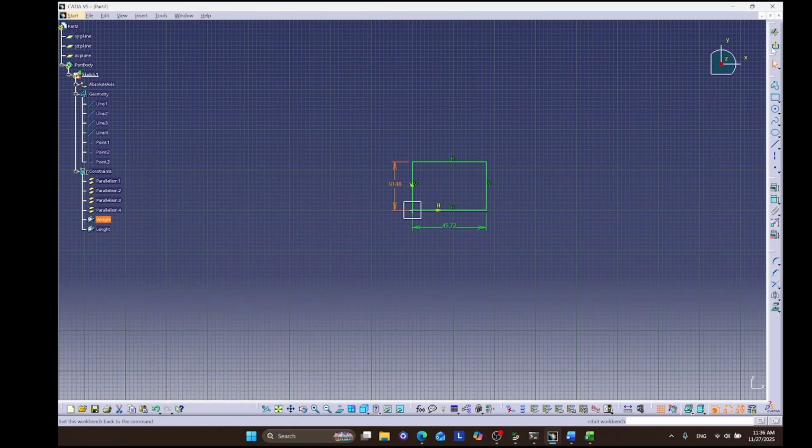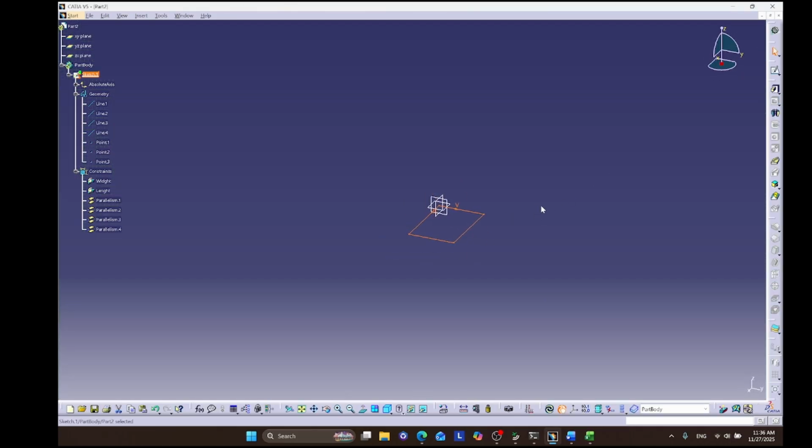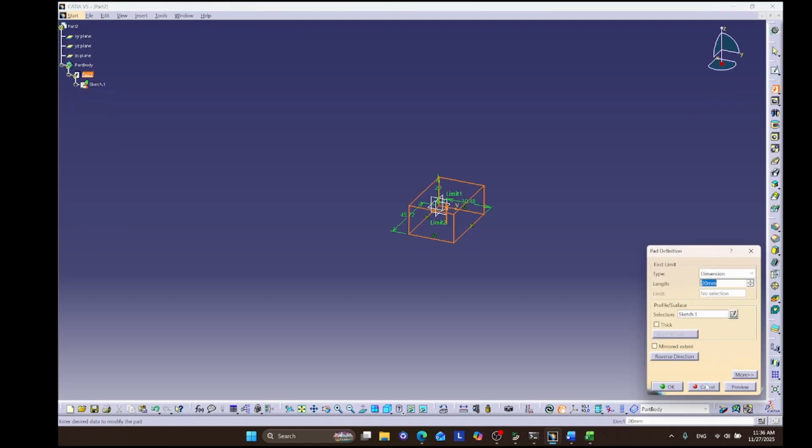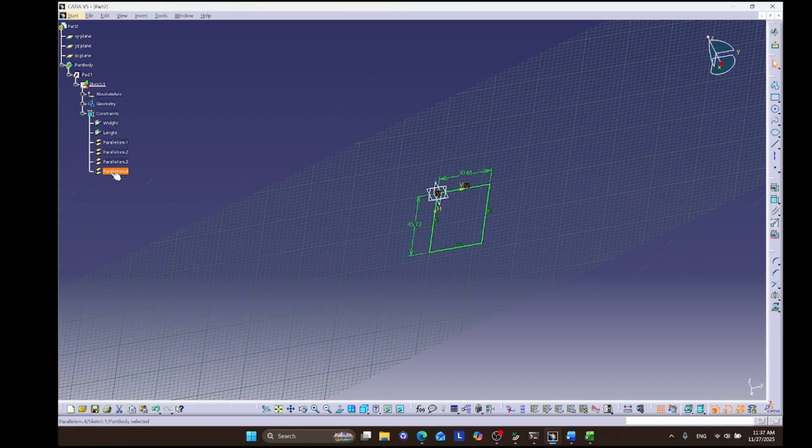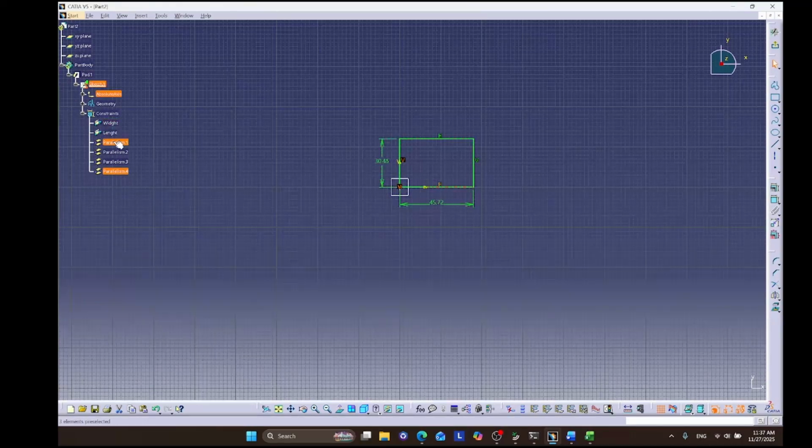And then next, you want to make it padded. Now you click on the Pad button. Just how much is okay. And you want to constrain it so you can make the constraint. Now, the pad length is different. You need to go to Sketch, Pad, go to Pad constraint.